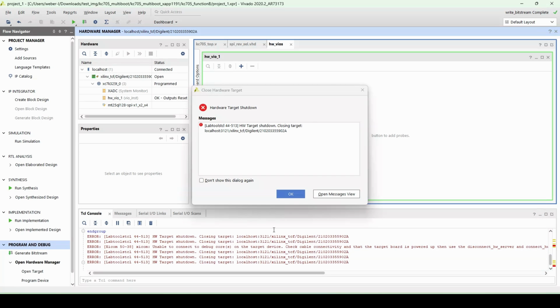Remember that this method needs to write to the SPI boot sector address 0. So it's okay to demo how the warm boot works, but it's a bit dangerous. In any case, if the write is broken, the board is easily broken. You have to use the JTAG to reload the board. So in reality, this method should be used very carefully.